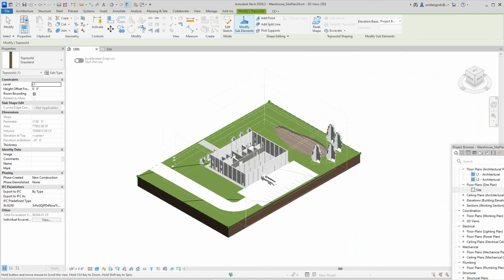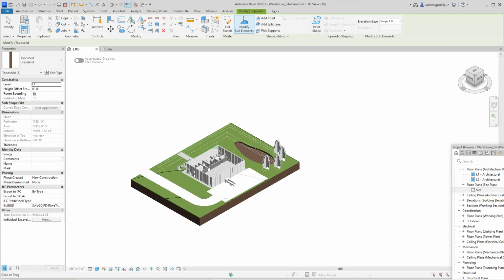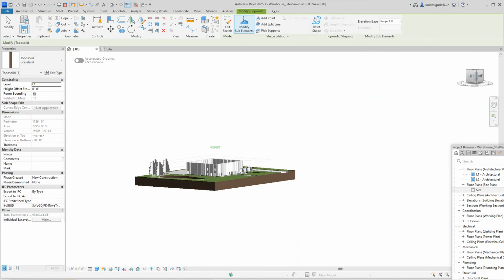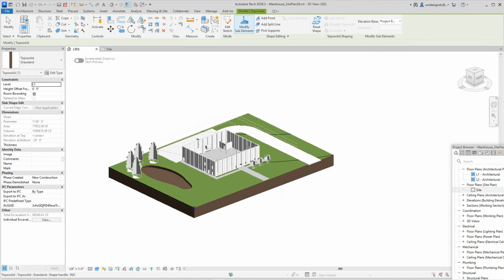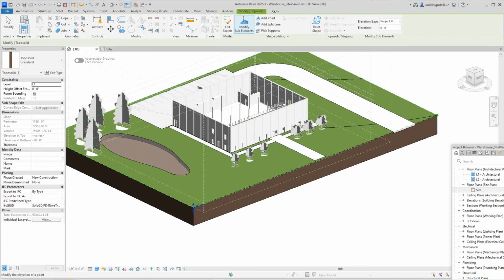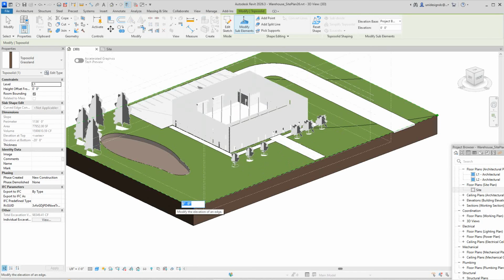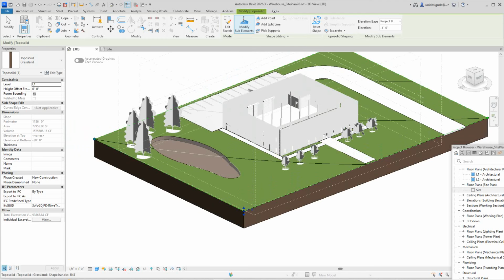Because we want to push the water away. Just like over this side, we want to drop things kind of low because we want that pond to collect the water from the driveway. So this one, we'll direct this one down to, let's make this a -1. And as you notice, the pool and everything goes down with it. You go there and here. We'll say this is going to be, let's make this 2.